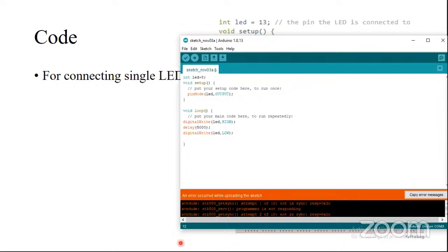See, compilation errors matter here, but this error does not happen in the compilation. When I give an upload, this error happens. But when I compiled, we didn't have any error. The one error we got was because of a semicolon. I put the semicolon, so there is no error in the code. We get this error because I didn't connect my board, but I gave an upload. That's the reason we get this error.